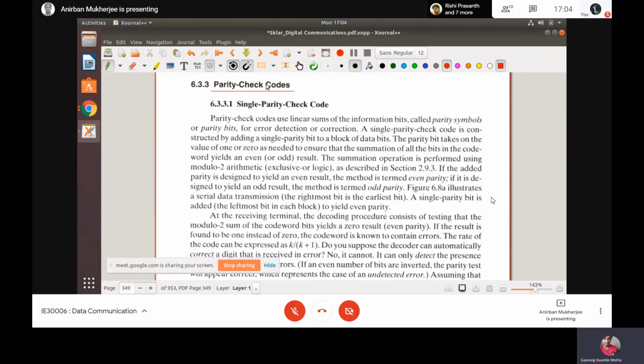So say 6 bits of data. Now, or say 3 bits of data. Then what I am going to do, I will append say 3 more bits, depending on the existing message bits, and the 6 bits I will transmit to the channel. At the receiver, he will examine those extra 3 bits that have been appended at the transmitter, and